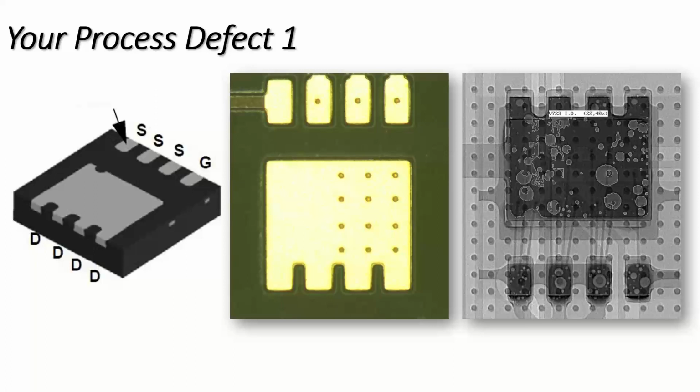So, things that can affect this, first of all, outgassing from the termination itself. If you've got a plated part, and if it's tin, as most parts are, sometimes you can get organics outgassing from the plated part itself, so the actual termination on the component. And I've demonstrated this on tin-plated components in the past. So a simple experiment is to just look at what's actually happening on the part if you reflow some solder on the termination. Just see if you can see any bubbling or gassing, and do that under a microscope, and that will allow you to understand potentially the problem.